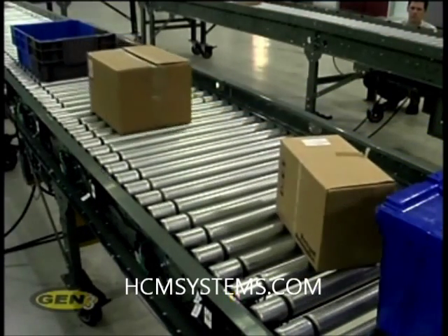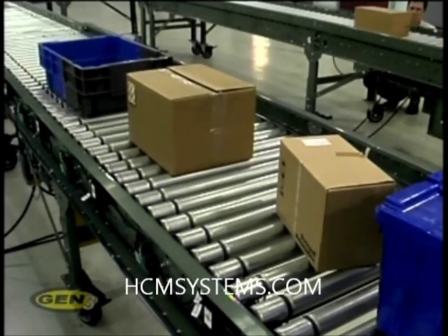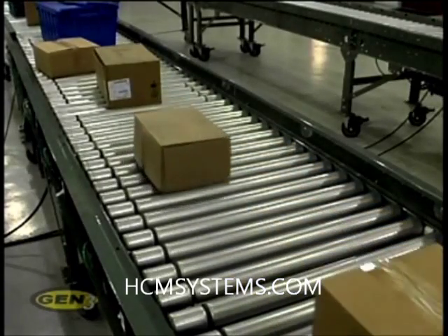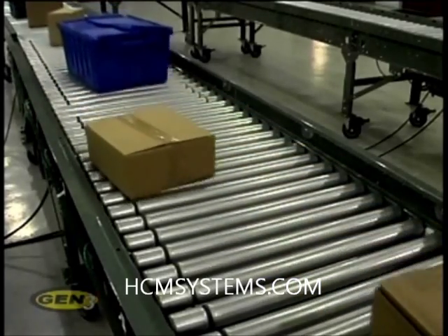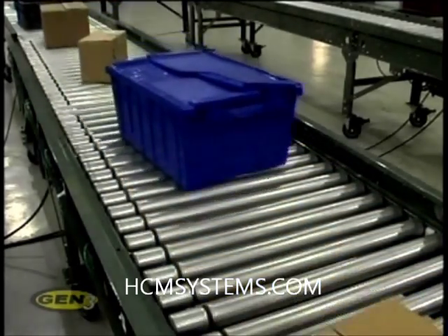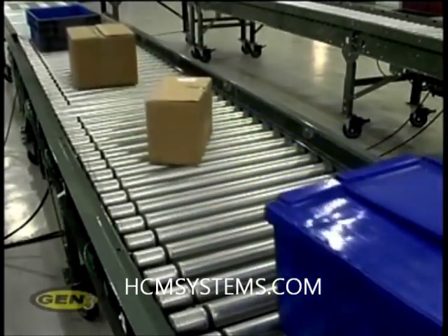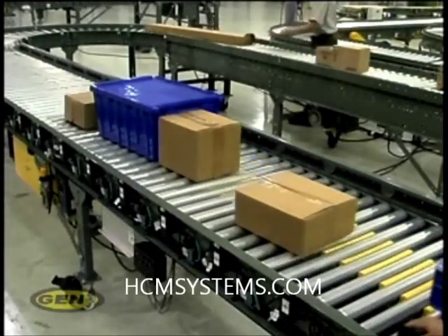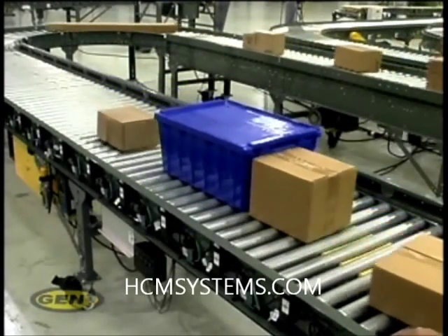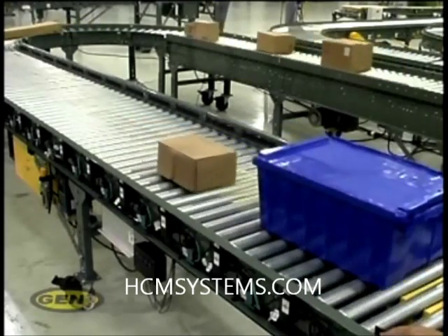There are two ways that EZLogic can assign zones to cartons. In fixed zone length mode, each carton is assigned one mechanical zone, the zone length determined by the mechanical build of the conveyor as it is transported and accumulated. When cartons are transported or released, a gap equal to the length of one mechanical zone is created between the cartons.